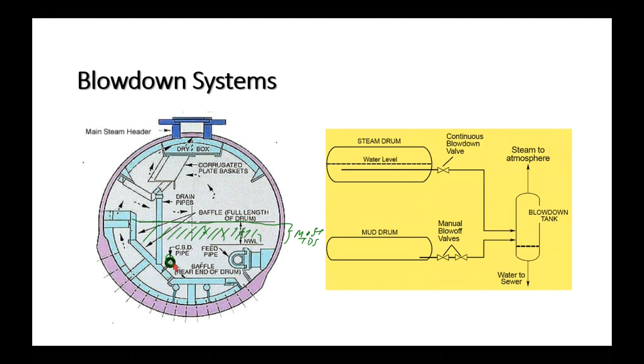So usually we see the continuous blowdown pipe somewhere within that top 6 inches or so of the boiler water level. And what is 6 inches? 6 times 25. You get the idea. You can turn that into millimeters if you think in millimeters.